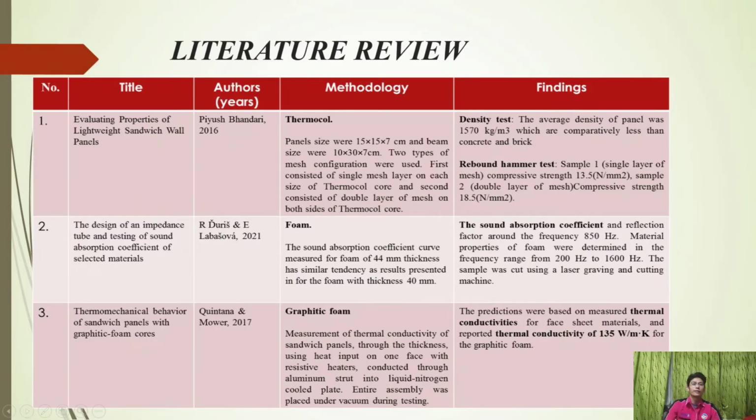Okay, for the literature review, the first is evaluating properties of lightweight sandwich wall panel, author Pius Bandari 2016. Methodology: thermocol panel size were 50 x 50 x 7 cm, and beam size were 10 x 30 x 7 cm. Two types of mesh configuration were used. First consists of a single mesh layer on each side of thermocol core, and second consists of double layer of mesh on both sides of thermocol core.